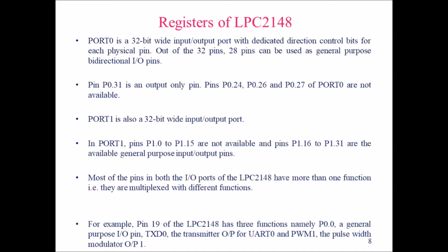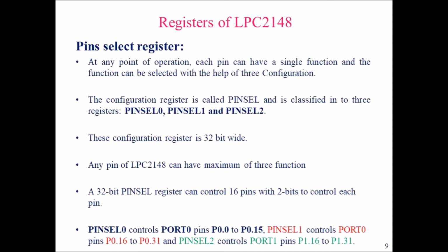Okay, so next, coming to the pin select register. As I told, each and every pin is associated with more than one function, so we have a pin select register. Let's see how the pins are selected using this pin select register. At any point of operation, each pin can have a single function, and the function can be selected with the help of three configuration registers.